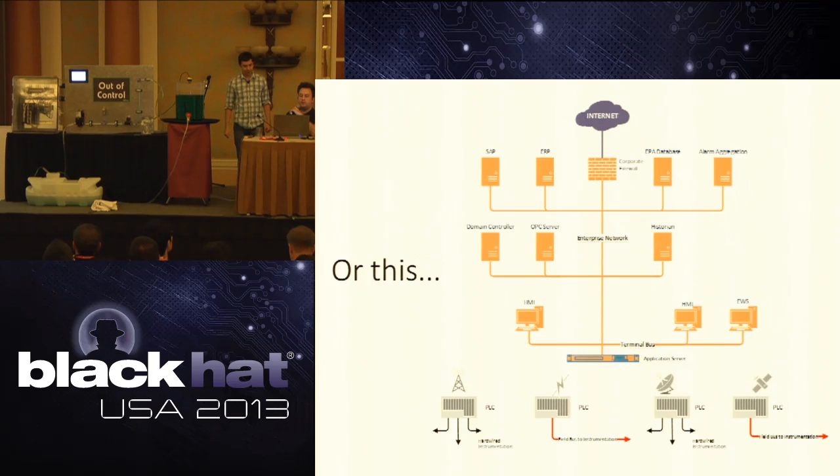And even worse is no routers at all, or no firewalls, where everything is on a flat network and everything can talk to anything else on the network. Yeah, anything from your SAP up to your web server can talk directly and is on the same LAN. So just broadcasting, it'll be on the same LAN as your actual PLCs and your controller hardware.